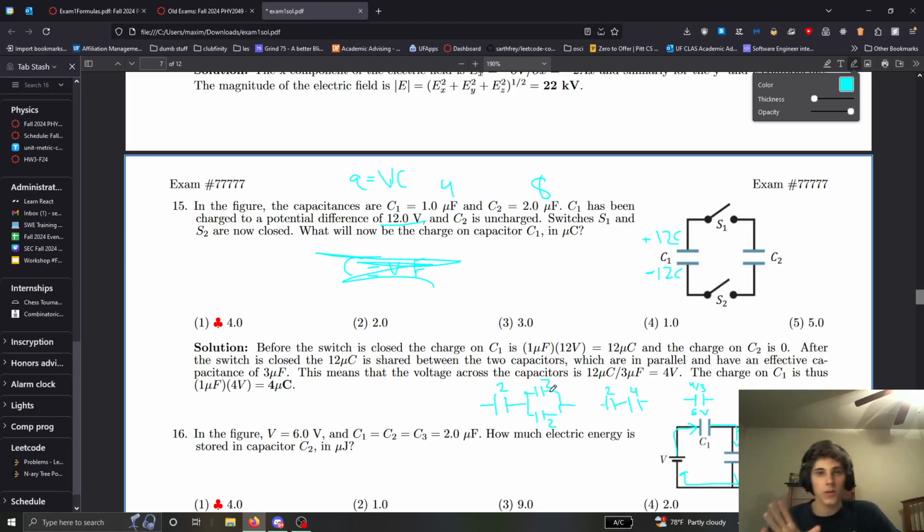Now, one thing that's not on the formula sheet, when capacitors are in parallel, like so, their voltages are the same and their charges add. When they are in series, like so, their voltages add and their charges stay the same. So first of all, the charge here, it's just the capacitance times the voltage is going to be 8 coulombs. And like I said, the 8 coulombs here will transfer, right? Both of them will be 8 coulombs. And then the voltage is dividing. So this is 4 volts, this is 2 volts.